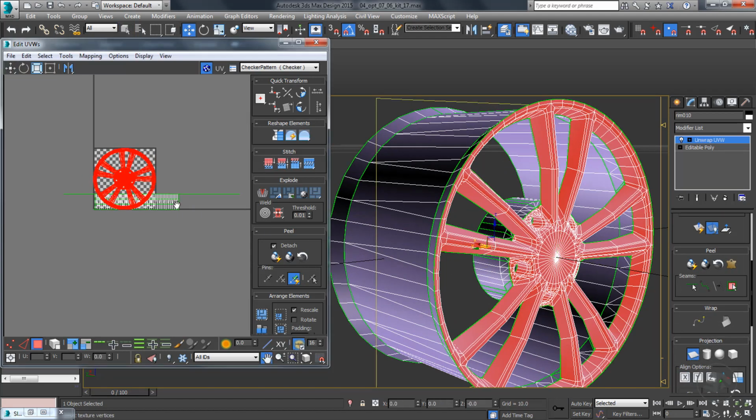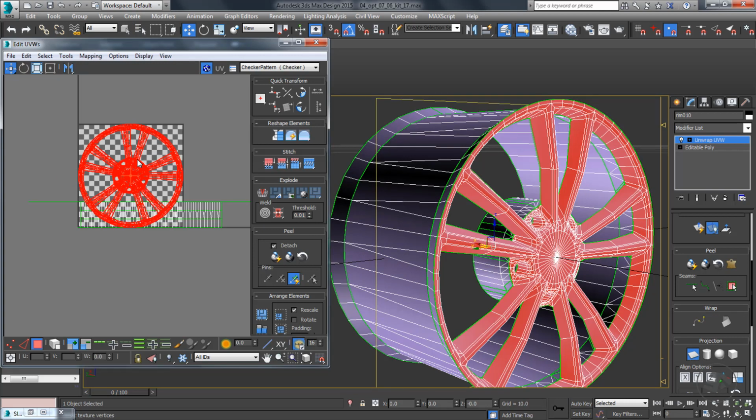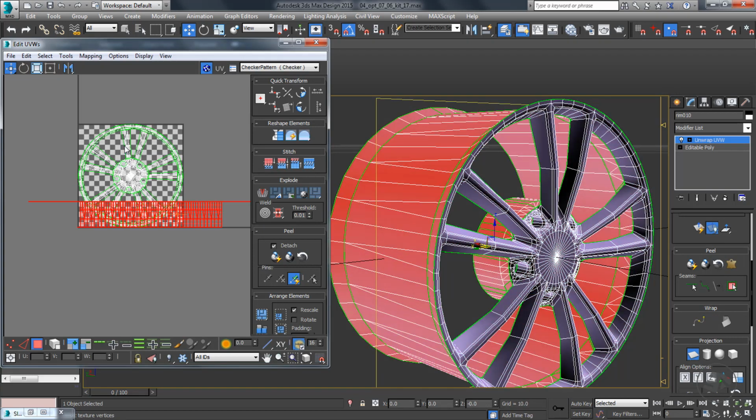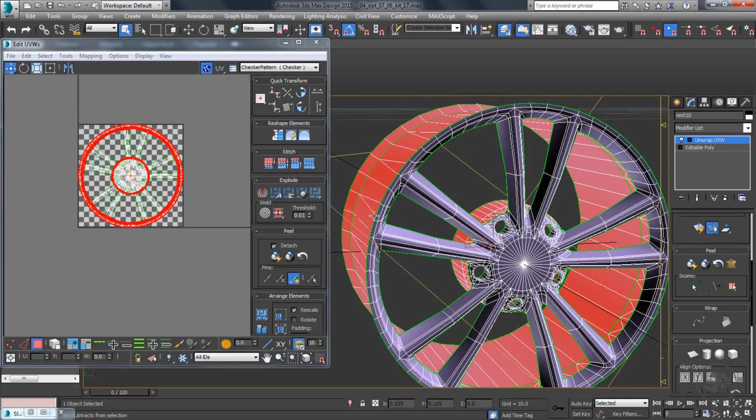This will flatten and unwrap these polygons at the x-axis of the viewport. It's like having a plane in front of the rim, flattened on the x-axis, and this plane's function is to capture a UV map from the currently selected polygons. Areas, such as the cylindrical part, or any other areas that do not contain details to capture, will be put aside.